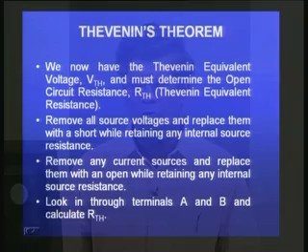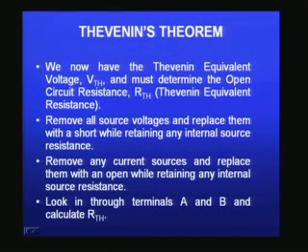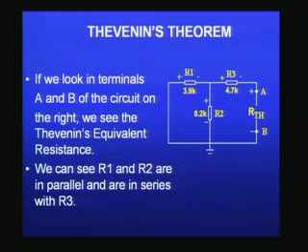We generally assume the voltage sources to be ideal for this case, and therefore, just remove the voltage source, connect a short, and then you have a very simple scheme of only resistors. And we will now calculate what is the effective resistance or Thevenin resistance between the two terminals A and B at the output.